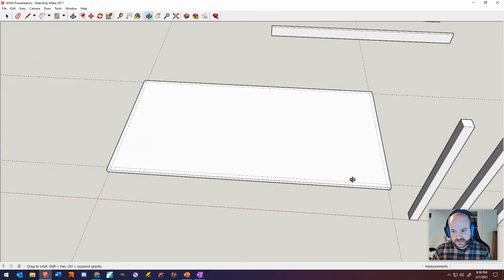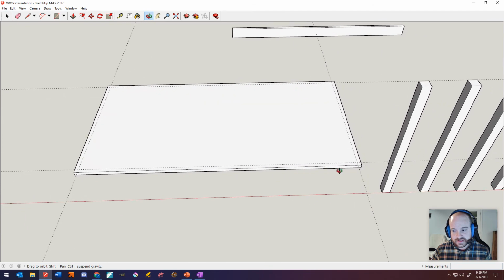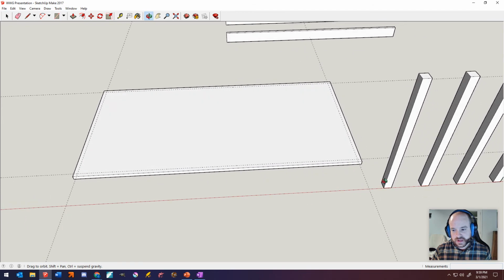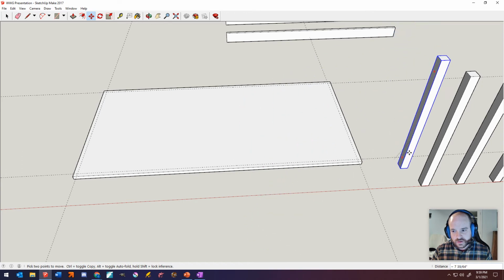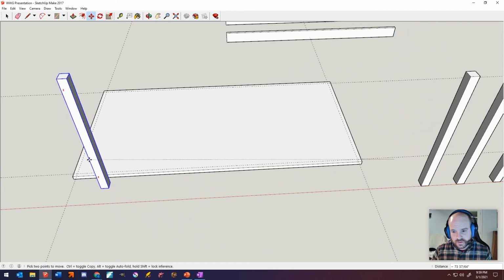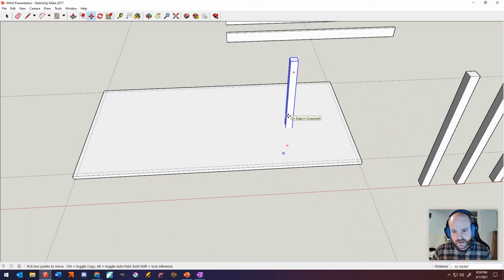And this, you guys, is the most important part of the whole stinking lesson right here, is how to get these objects to line up right. When I hit space and I select this object, you always look for the corners. If you hit M for move and you try to grab this thing, SketchUp doesn't know whether you want it to go vertical, doesn't know whether you want to go horizontal or whatever. And if I just drag it, it's going to put it right in the middle of the object. SketchUp needs help understanding where you want to place it.